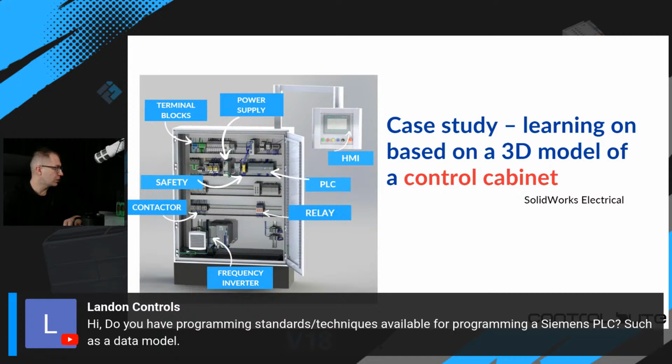I have a question here. Do you have programming standards techniques available for programming a Siemens PLC, such as data model? In our courses, we use standards like PLC Open. PLC Open is a standard for designing programs and function blocks, and we use that in our programs. What's more, we use the PackML standard for packaging machines, and PackML describes sequences for machines.